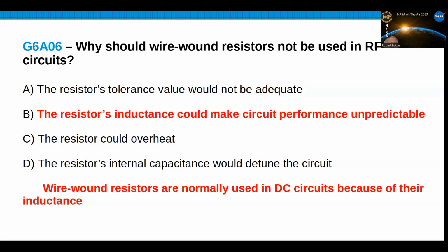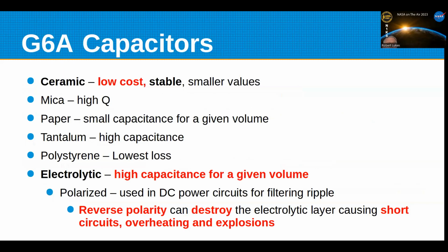Okay. So we don't want to use wire wound resistors in RF circuits. It can give unpredictable performance.